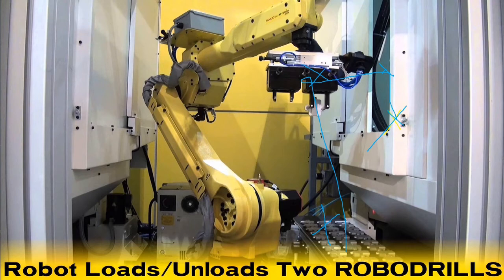Or if there's a couple more obstacles that we might need to twist this arm around very carefully, then point to point could result in a crash. So if we need to start twisting the arm and very carefully back the robot out, then a continuous path might be more applicable so that we can make sure that we're navigating those obstacles. We might not need a controlled path necessarily. That might be overkill. I think a continuous path would work just fine here, so that we're navigating through this tight space, but it's still very basic linear motions.